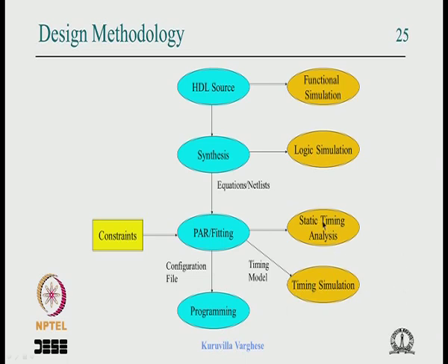But here what is done is that this tool will look at the block delay, interconnect delay, and estimate the time from input to output for a combinational circuit, or for register to register for a data path or sequential circuit. But the problem is that there are no inputs. No inputs are specified, so the state machine or the controllers are not active.